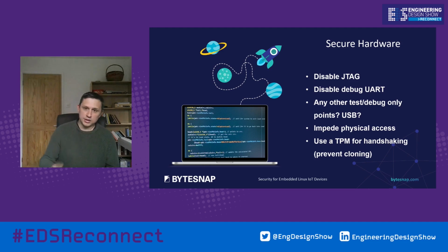So you really need to make sure that you're disabling the UART port entirely, or at least the input. Actually, a lot of modern security requirements will require any unused interface to be turned off, so you really need to close off the whole thing.